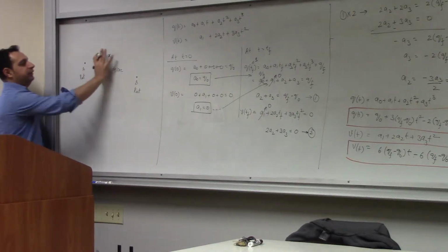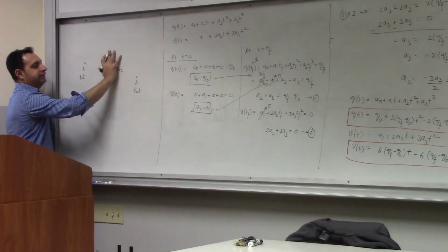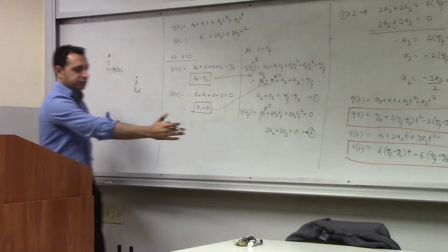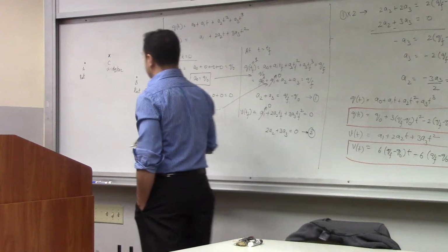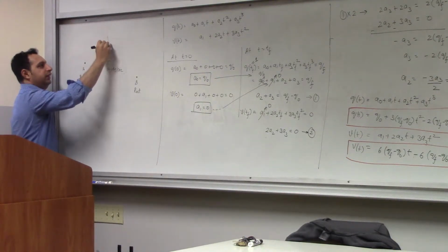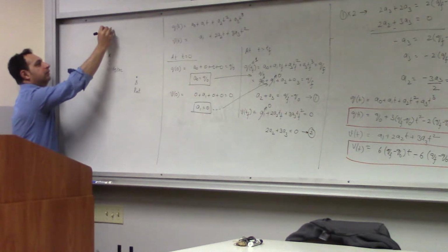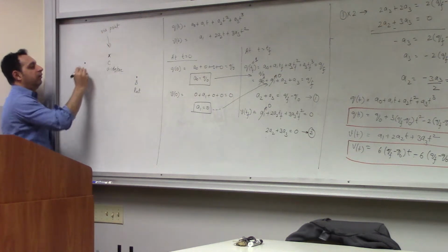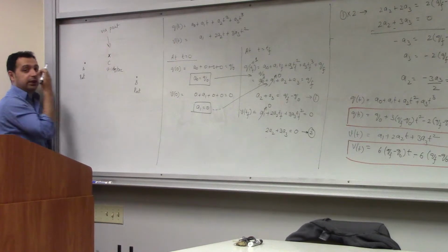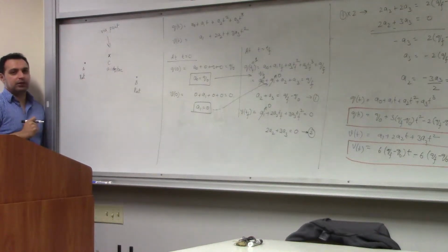Usually if point C was not there, I'm starting from rest and stopping at rest, you can use one of these polynomials and you can do it. But if I'm stopping in between, this is a via point. So I want to go through this point, and at this point I want to maintain a velocity of 1 degree per second. How do I do this?